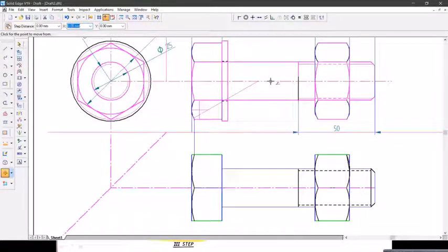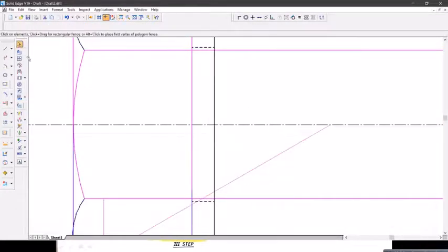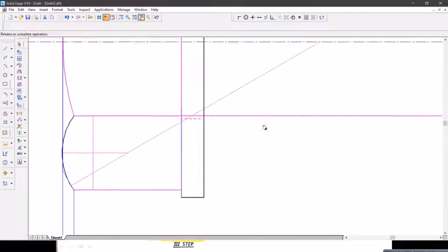Then select this as a center point and we place exactly perpendicular. Copy these two lines again. Now it is difficult to get these smaller objects because if the snapping point is entirely different, you will get a little bit confusion.